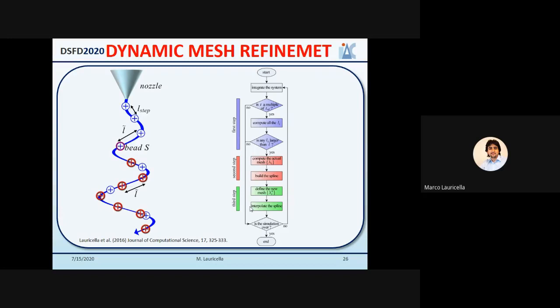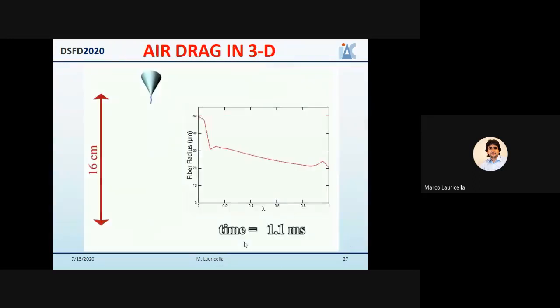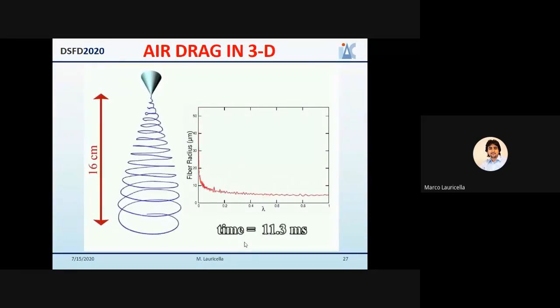the old mesh to build a set of cubic splines for each independent variable. Then we define a new mesh with the desired resolution. Hence, the new values can be obtained by interpolation from the cubic spline, and we can repeat this process dynamically every certain time interval. So all these tricks allow us to simulate the entire process.